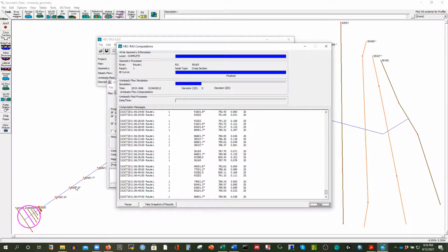So whatever the time step is, it won't change that much. So you don't need to reduce your time step and increase your computational time, and it is just going to create a bunch of data. Your output volume will be big. You don't need that because it's going to repeat the same thing, and pretty quickly we can see what will be the output of this, and we can see the animation as well.